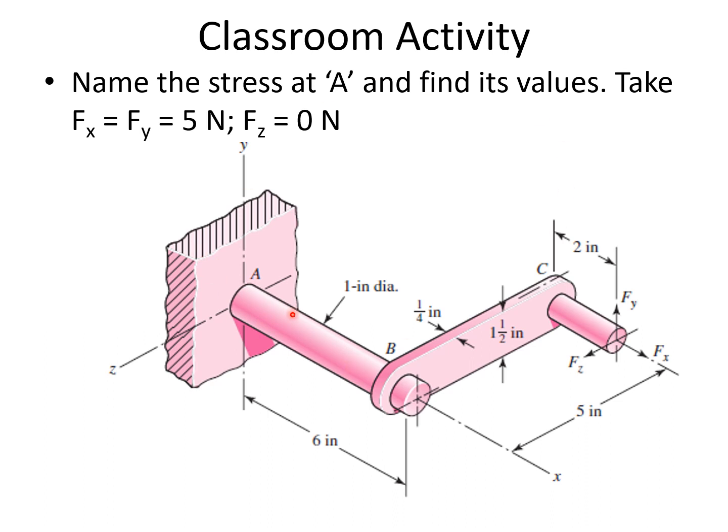If this is the case, then you have to say what are all the stresses at A. Say, first consider Fx alone. Due to this Fx, the whole member will be pulled. So at A, you may experience tensile stress, and if you are applying Fx directly here, you will experience only tensile, but you are applying with some eccentricity.